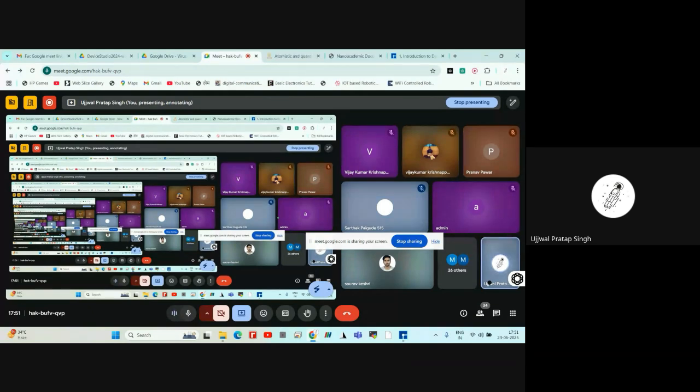I hope everyone followed the steps to create a structure, their crystal, import material. In today's session, basically we went through the toolbar and GUI of Device Studio. In tomorrow's session, we will go through the RESCU software, which is for material simulation based on DFT and density functional perturbation theory, where we can find band structure, molecular potential, effective potentials, phonon, optical properties, dielectric, Raman spectrum. This type of data we can find tomorrow.